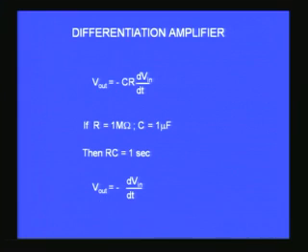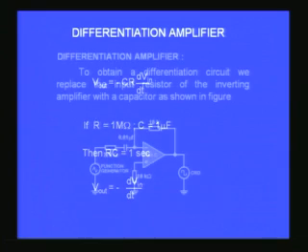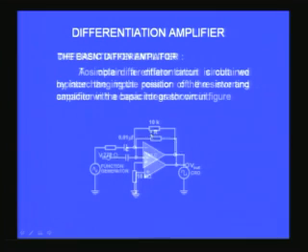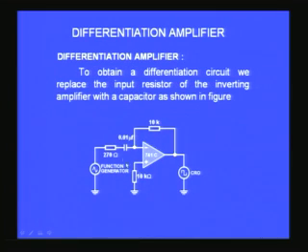Right. Now I will explain to you about the circuit. This is the basic circuit which involves one capacitance and one resistor, but it is slightly modified here for a very specific range of frequencies in the range of 1 kilohertz, and so you find I have used a capacitor whose value is 0.01 microfarad and a feedback resistor which is 10k, and I have also used a very, very small resistor here, 270 ohms.